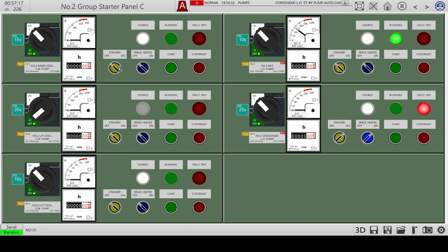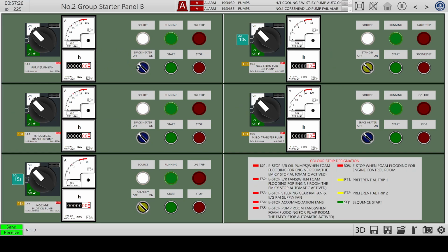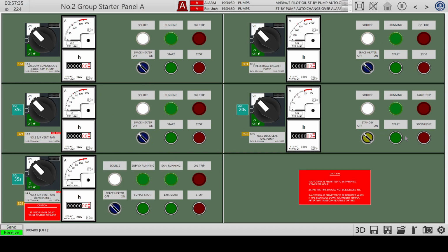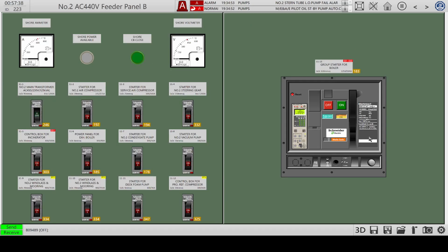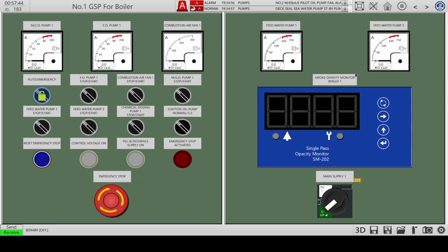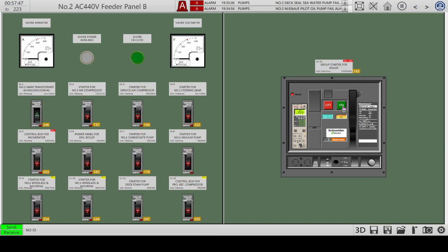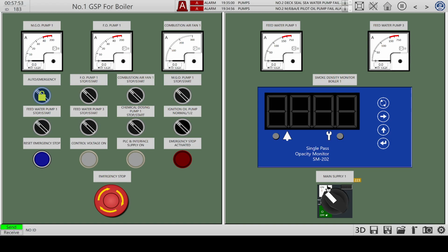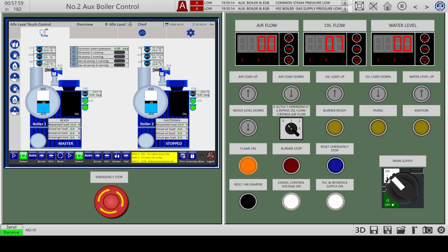I should put them on standby, so if they need it, they can start up. But this was the main breaker that I was looking for to provide power to the boiler systems. To enable it, close it, I should say. And now we can close this breaker and we do have power to our boiler systems.